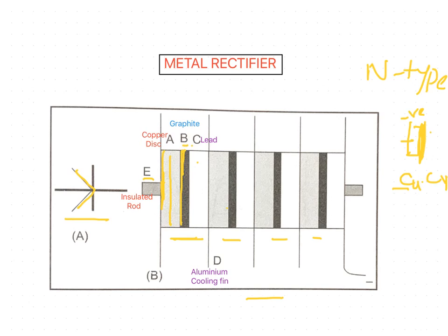Selenium rectifiers are also used. Selenium is a p-type semiconductor, and a tin alloy in contact with it acts as n-type. The rectifying units are separated by appropriate materials and each one will rectify up to 18 volts.